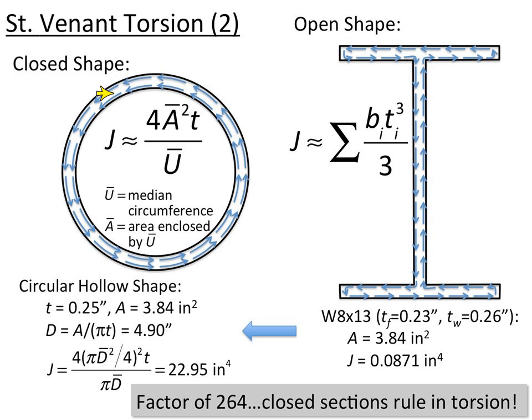And so if you're having a look at that, you're thinking, whoa, the enclosed area is getting squared. So you're getting a lot of J. Compared to that, the only thing that's getting cubed or amplified here is the thickness, and that number is usually pretty small. So you're taking a small number and cubing it, it's getting even smaller.